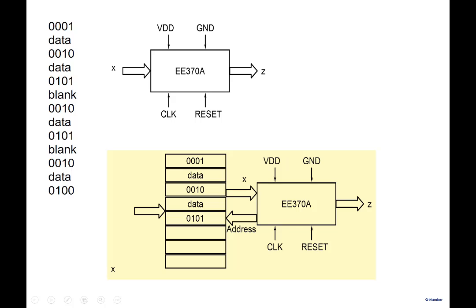Now from which register will it come? When you have a set of registers, let's say 16 registers, I require an address. Which register is going to give the data here? So I need an address here, and who decides the address? Well, this IC will send the address here, and depending on the address, the data is read from here or here or here. So I have a set of registers in which I load my program, and the data will come from here. Now I have to modify my IC also, so that it generates a register address and can handle this.